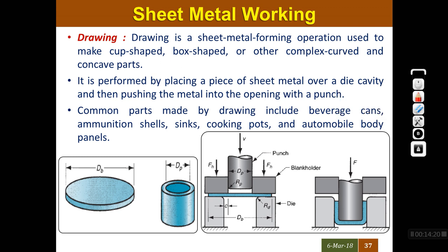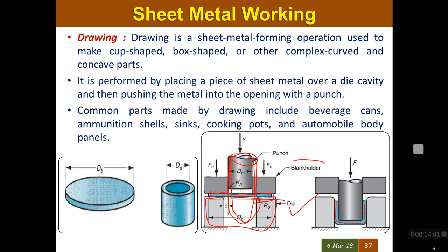The important thing in this diagram for sheet metal operations is that we have these two dies, a die which is the stationary part, and this blue color is the metal sheet, a thin section. To form the metal sheet into a U shape, this cup, supporting pressure pads are required, which are called the blank holders. To hold this blank, we require this force to place the metal sheet in the respective position, and that is called the blank holder.